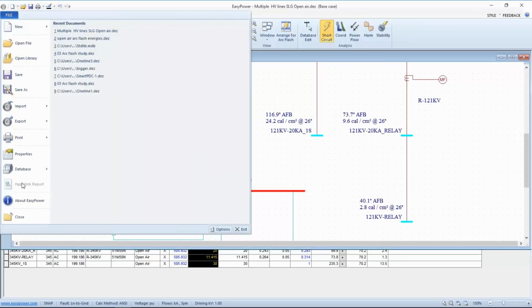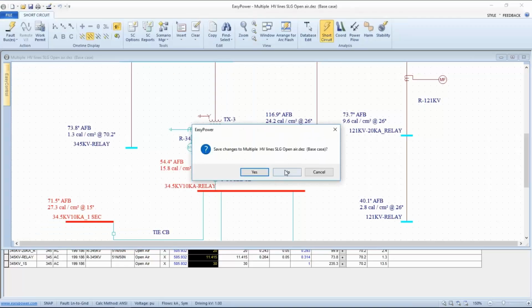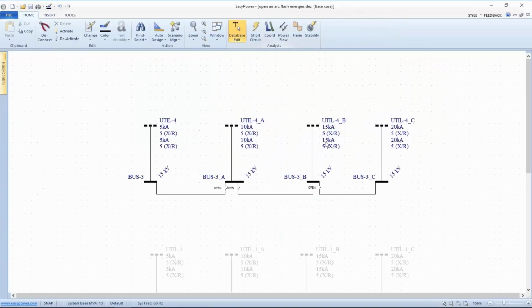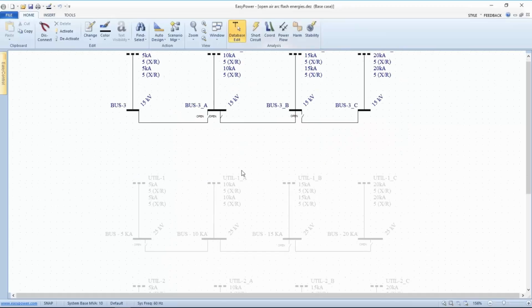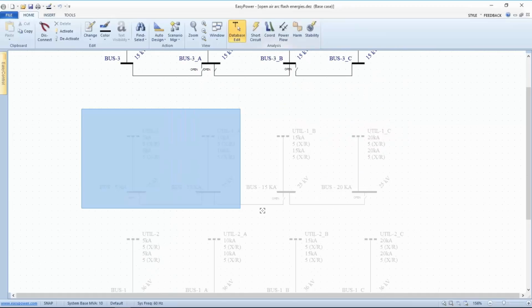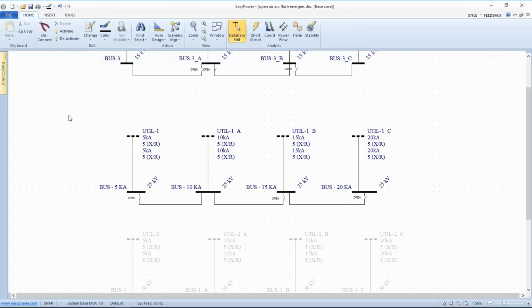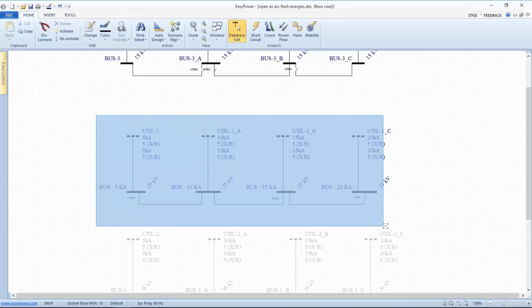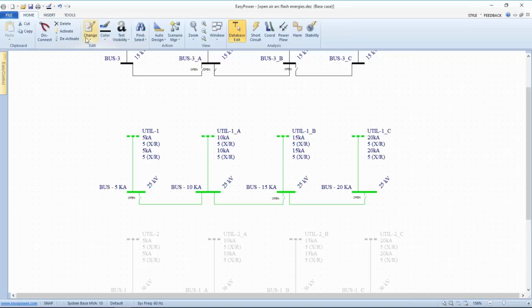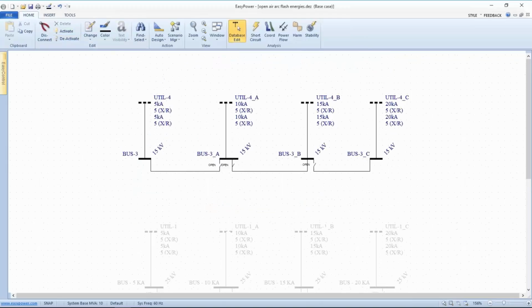And this is kind of clever. And so what I've done, I don't know if you can see it, I've got all of these voltage ranges set up in the tool, and I just deactivate all but the one I want to look at. But in essence, what we're doing is we're setting up this utility for 25,000 volts and set up to supply 5,000 amps, and I'm using just a 5x over R to make it simple. So I'm going to go back and deactivate this so I can look at the results here.